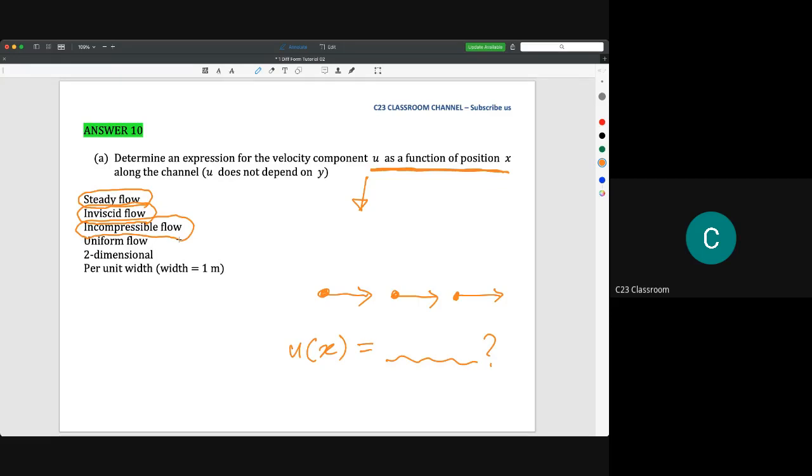Another reason is we cannot use the Bernoulli equation to calculate compressible flow. That means your knowledge about how to calculate the flow, the velocity, and the pressure is not ready for compressible flow problems. That's why almost all the situations we handle are incompressible flow.